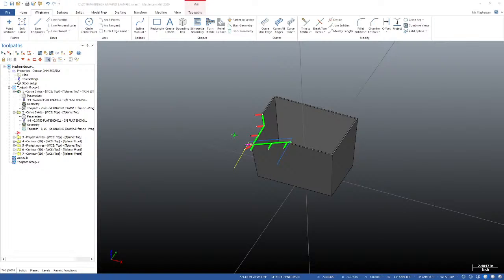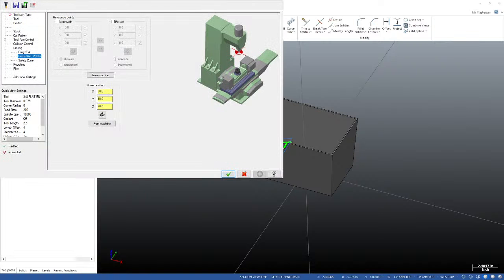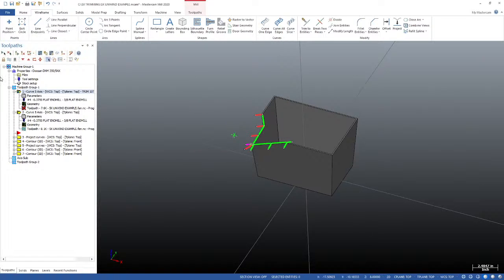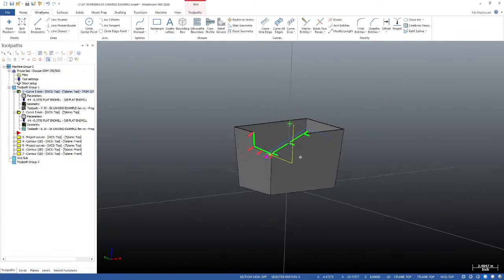hold on, let me, there it is. So I'm going to go up to my retract point, and I'm going to go to the select button here, and I'm going to grab it. And you'll see that it's also relative to the plane that I've got selected down here. So really the 8 inches, the 8-inch Z position is the critical part. So I can turn off the X and the Y, and if I regenerate, what you're going to see is I make this cut down here, I retract out along the tool axis, but then I pop up over here.